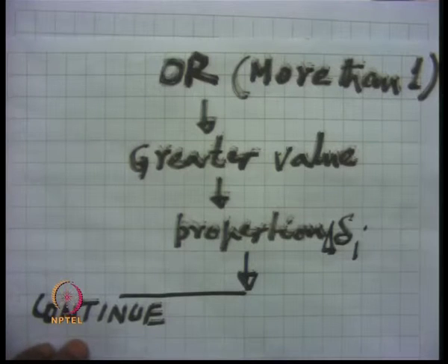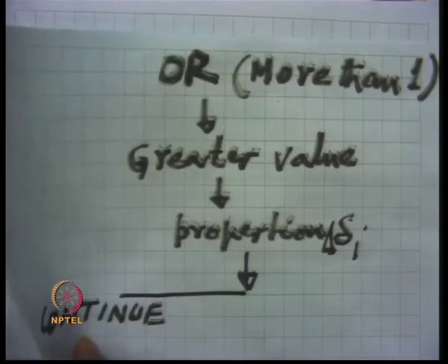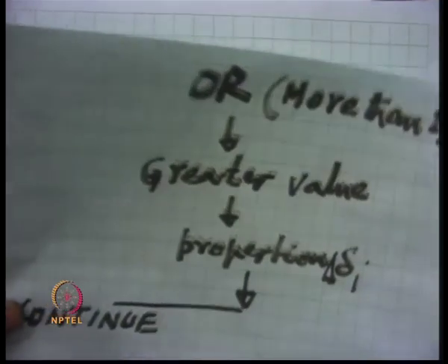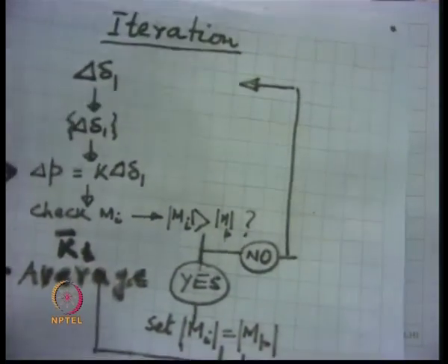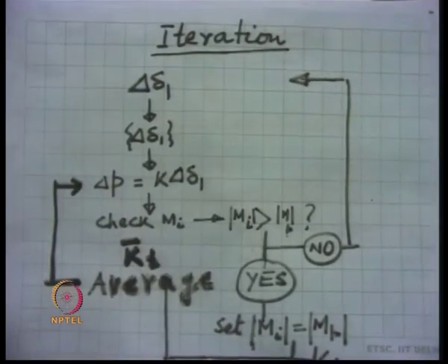This kind of calculation may require a little more time to trace the load deflection behavior. It is better that one goes for an average stiffness technique to take care of this kind of situation.